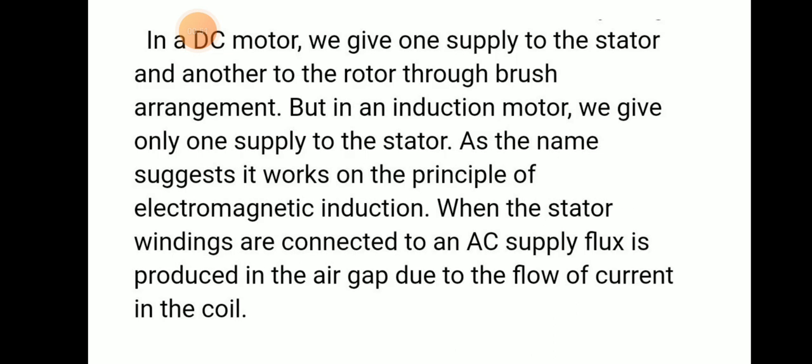In a DC motor, we give one supply to the stator and another to the rotor through a brush arrangement. But in an induction motor, we give only one supply to the stator. As the name suggests, it works on the principle of electromagnetic induction. So, when the stator windings are connected to AC supply, flux is produced in the air gap, and due to this, flow of current will be happening in the coil.